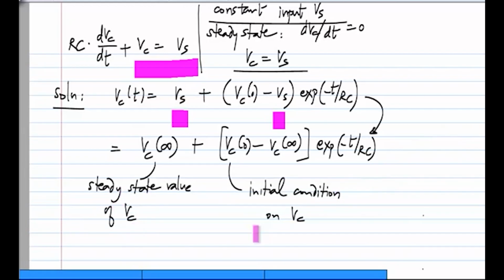So now this is a general form of solution to any first order circuit. We have been looking at RC circuits, that too with a single R and C, but as long as you have a circuit with either a single capacitor or a single inductor, the rest of the circuit could be as complicated as you can make it. Okay, you could have any number of independent sources and linear elements such as resistors and controlled sources. We know from Thevenin's theorem that all of that can be reduced to a single voltage source in series with a single resistor at the terminals of the capacitor, and if you have an inductor, again the same thing can be done. So the result is a first order circuit. The solution to any variable in such circuits will be of this form.